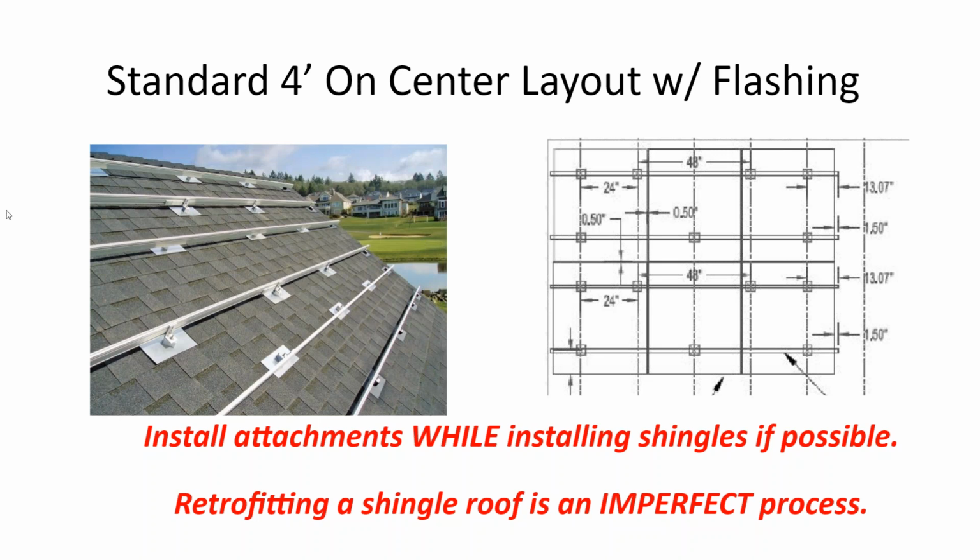So here's kind of a completed product where you have this technique. This is where pro residential solar installers eventually get to, because what you have here is spacing requirements that are within the parameter of the rack. I'll show you how to do that tomorrow. But then the installer also recognizes that this might be a 4-foot span between point A and point B, but the rafters might be 16 inches apart, so if we just stuck to the 4-foot span, we would be skipping rafters.